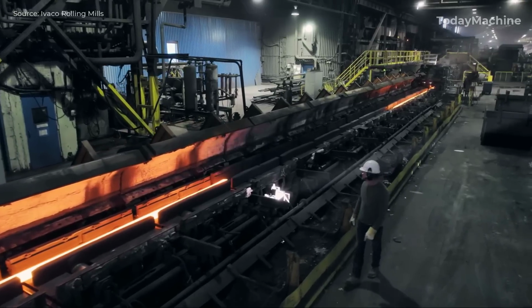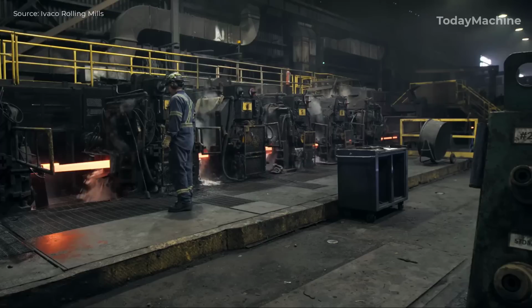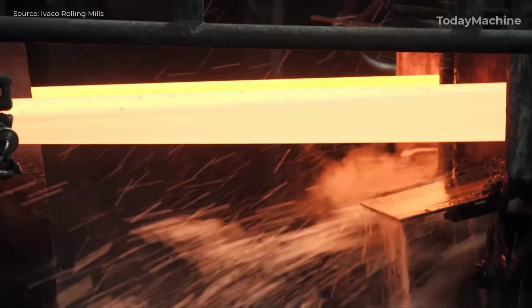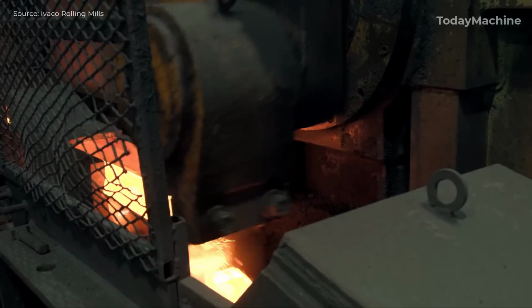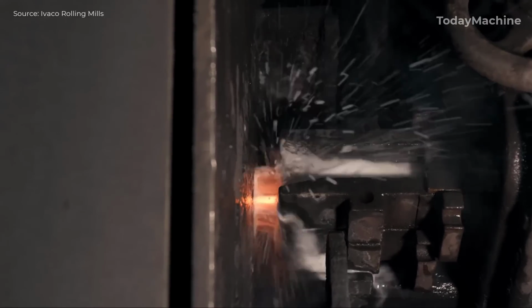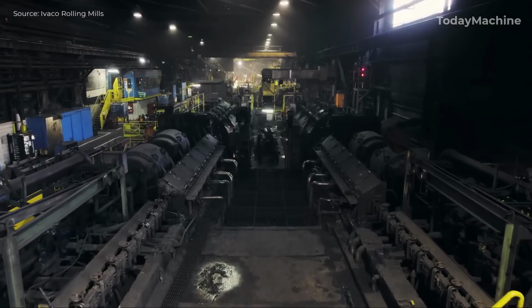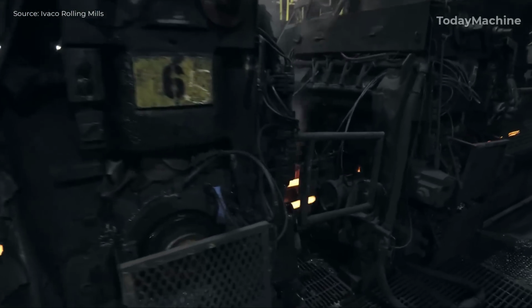Shaping and finishing. After passing through the breakdown mill, the bars are directed to the roughing, pre-finishing, and finishing mills, where they undergo further reductions in diameter. The bars can pass through up to 24 sets of rolls, with each stage progressively reducing the cross-section and increasing the length of the bar. Throughout this process, the bars are cooled in enclosed water boxes to ensure the steel's internal structure is optimized according to customer specifications.